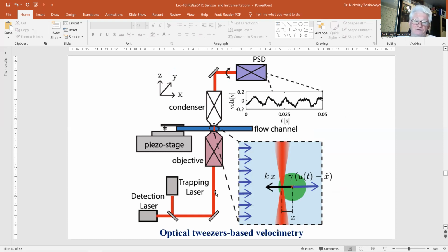Apart from time filtering of the reflected signal, spatial filtering is another useful approach. The moving object is illuminated by environmental lighting, so not necessarily coherent light. The illuminated area is viewed by a photodetector through a grating with small periodicity p.